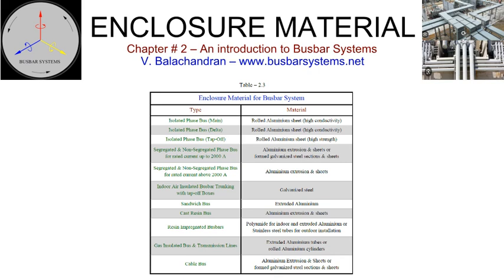The enclosure needs to withstand very high electrodynamic forces. An aluminium alloy enclosure material with a lower conductivity, in exchange for a higher mechanical strength, is in order as long as it meets the specified temperature rise requirements.